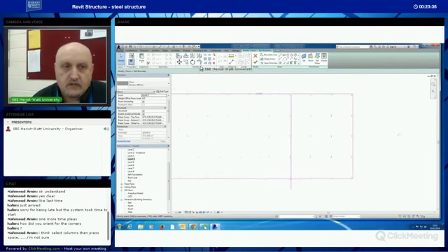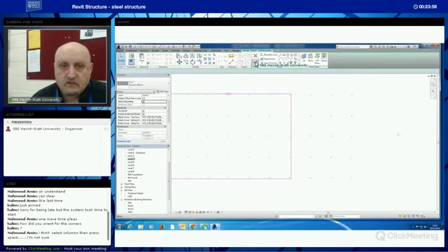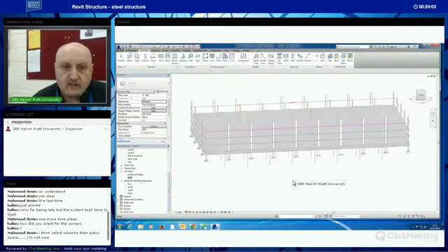And then I'm going to use this tool here, which is a trim and extend to corner tool. It's a great wee handy tool. Select that tool there. Select the lines you want to keep. I'm keeping this and I'm keeping this. This goes. And I'm keeping this one here and I'm keeping this one here. So anything down here goes, and this one simply gets deleted. Oops. Select it and delete. And finish off your new floor. Check it in 3D.